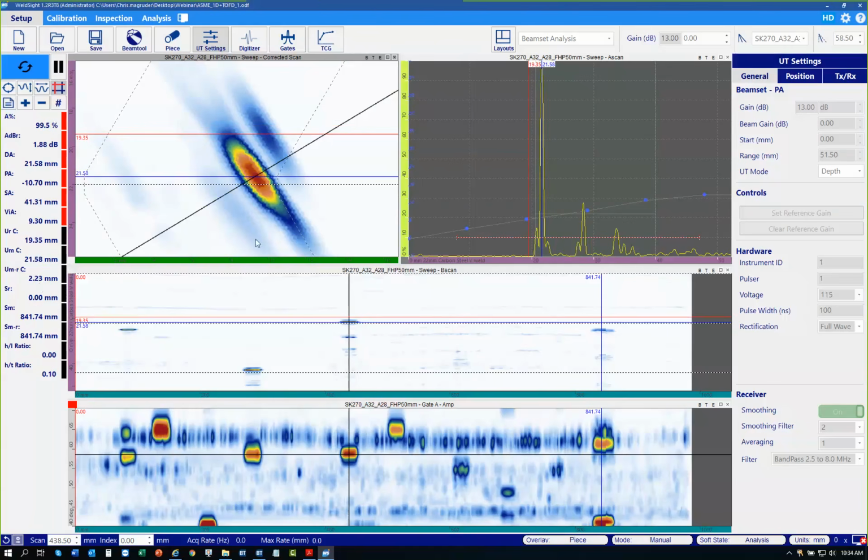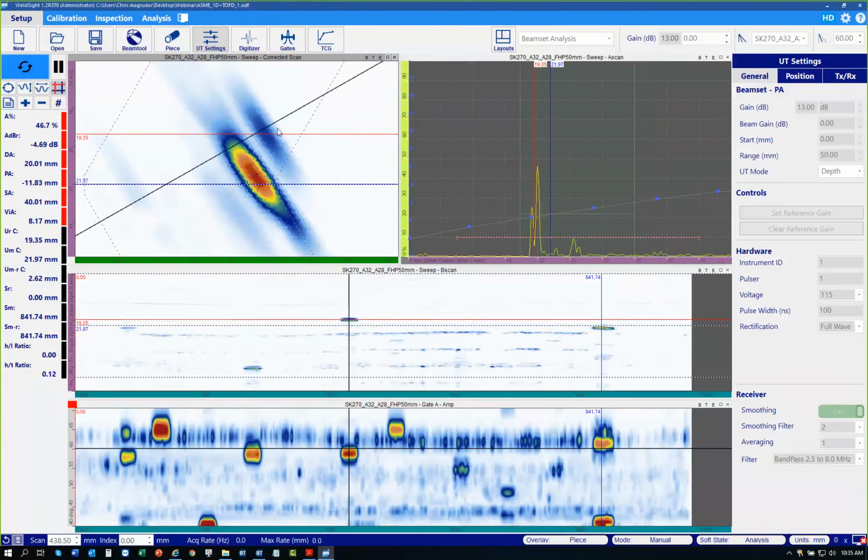Okay, if I were to put this cursor here on the bottom, assuming that we know the thickness of this, the tip measurement now becomes the absolute arrival time, meaning that we're only taking this through wall dimension and we're assuming it's connected and measuring it from the bottom directly here.